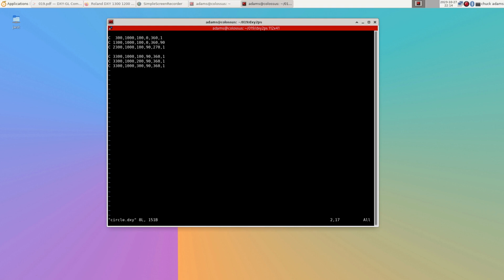If you want to draw an entire circle, you start at 0, which would be the right-hand edge, horizontal from the center point, and we'll go from 0 to 360, and that would be drawing it counterclockwise, and I do it in 1 degree increments.